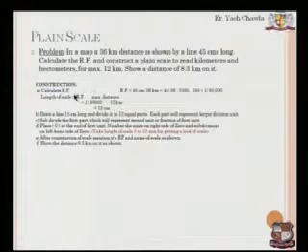So for calculation of RF, again I'll say what is my drawing scale. It is 45 centimeters, so I'll divide it by 36 kilometers. So my ratio will be 45 by 36. Now the 36 kilometers have to be converted into centimeters. First I convert it into meters, so I'll multiply 36 by 1000, so 36,000 meters. Then again, 1 meter is 100 centimeters, so I'll again multiply it by 100, so I'll have a scale of 1 upon 80,000.